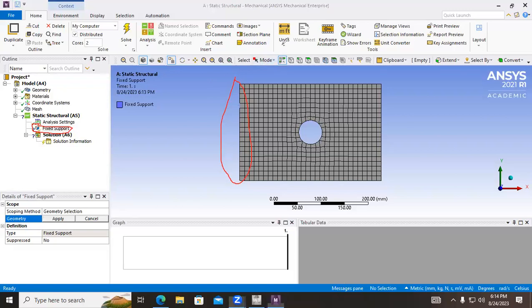And so if you go to this part of the screen right here, you can tell Ansys to snap your mouse to certain kinds of entities. And so if you click on this one right here, which is the box with just the green line on top, this will tell Ansys that you want to snap to an edge. And it'll be a lot easier to click on that edge. And so even with jittery hands, you can.